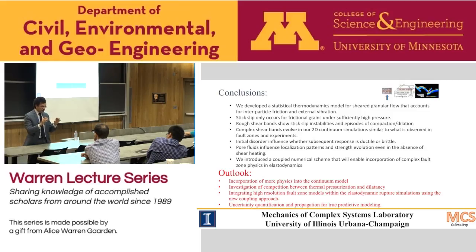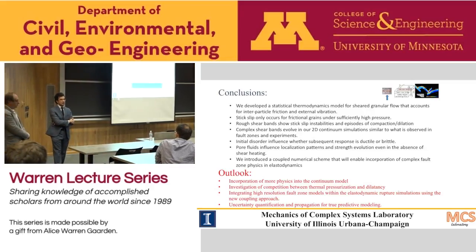So for that purpose, we thought that, first, the boundary integral is an exact or transparent way to propagate waves. We even think that we can put a discrete element model in that mesh, and if we have the boundary integral discretized well enough, it can propagate these high-frequency waves and it wouldn't be a problem. So first, it's a transparent way to propagate the full spectrum of the wave field. But it's also because we have this infrastructure in the earthquake community of doing the spectral boundary integral equation, at least me, because I was also co-advised by Nadia, so we learned how to use the convolutions and do it in the Fourier domain. So we think it would be an easier way for the earthquake community to use this coupling than quasi-continuum or something. But the fundamental difference is we have a transparent condition for the wave propagation.